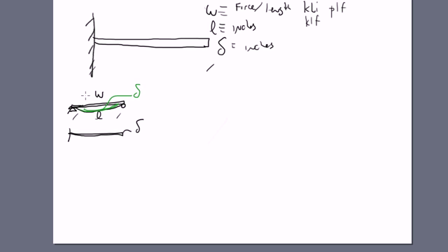So the formula for the deflection of a simply supported, uniformly loaded beam was that deflection max is equal to 5WL to the fourth power over 384 EI. And you remember that the cantilever one was going to be essentially almost 10 times as much, or 48/5 of that.